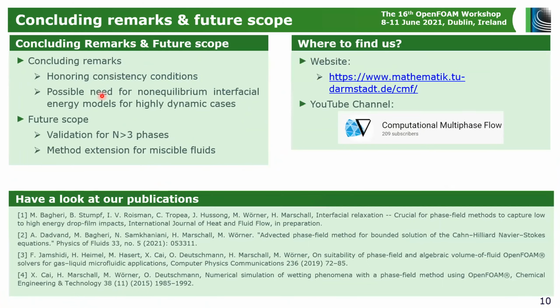So we just have a minute left. Okay, so concluding remarks: we need to honor the consistency condition. We have noticed that at higher speed, at high dynamics, we need to account for non-equilibrium interfacial energy, which means non-equilibrium surface tension contribution. We are validating our solver for more than 3 phases, and we are extending our solver to cover miscible fluids.